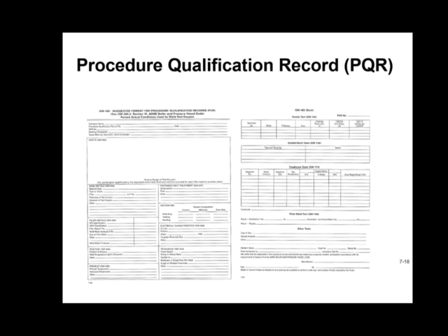If you don't do something, do not put NA. Like post-weld heat treatment, use the word none. If you did not use post-weld heat treatment, put none. Don't put NA. It is applicable, and you just didn't do it. None is better than NA. A lot of times when you're sending these in for review, somebody is going to look at it and say, he put NA, he should have put none. You need to put none. So don't fill in all the blanks.